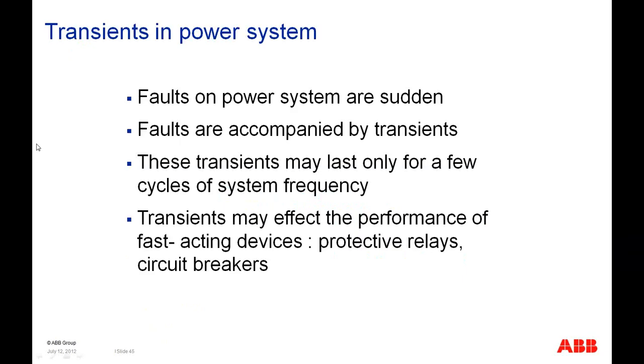Next, we'll go through CT transients. Faults in a power system are sudden and are often accompanied by transients. And as we said before, we want these current transformers to accurately reproduce what's going on in the primary system with very little phase angle error or magnitude error.